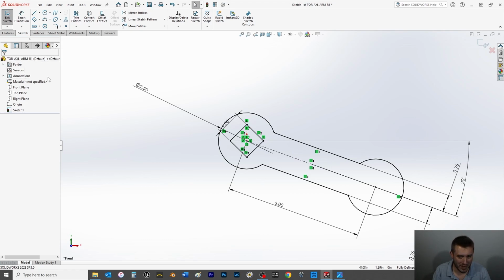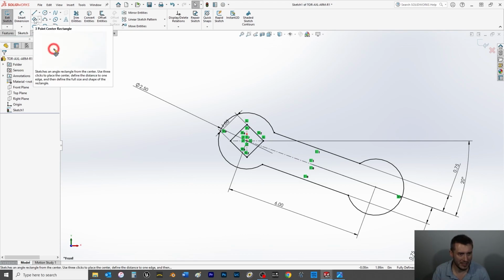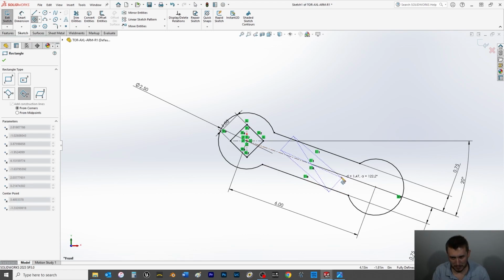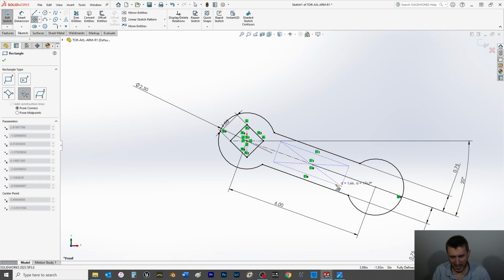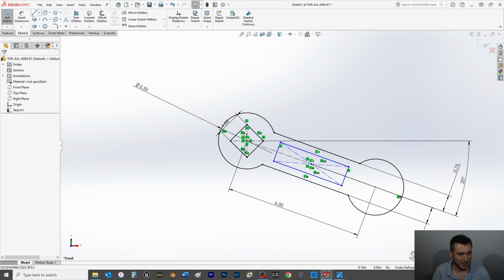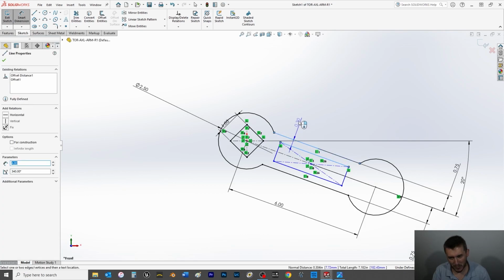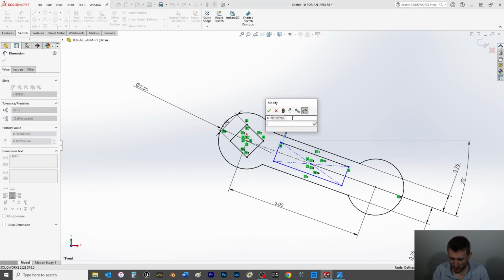Now, we'll do all of this in mostly one sketch. I'll make the axle coming out for the actual wheel a secondary sketch, but within this one, let's do this. Actually, we could just drag straight out on that. There we go. I'm going to do a little bit of an indent. How much? Let's just say we'll offset it from this. We want this dimension to be based on this external line here, so that if we ever change this width here, this internal indentation will change relative. So we'll make that 0.375.